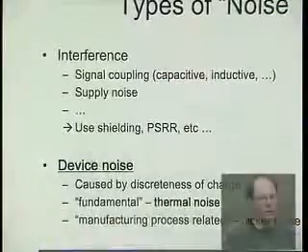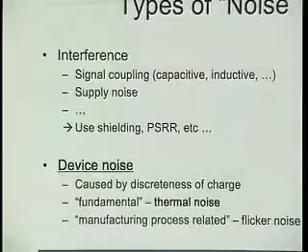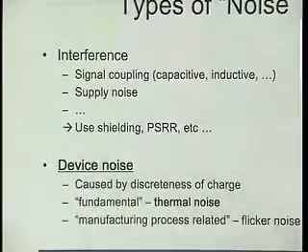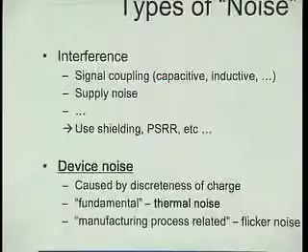And there are a bunch of other reasons we can imagine, right? The light coupling. Yeah, sometimes when you go to a lab, you see a dark cloth draped over a chip. Well, why is it? Well, because of the photo effect, right? If you have an exposed junction, you generate electron-hole pairs, and they add extra current to your signal that you probably wouldn't want to be there. So sometimes engineers work in the dark, under a dark cloth.